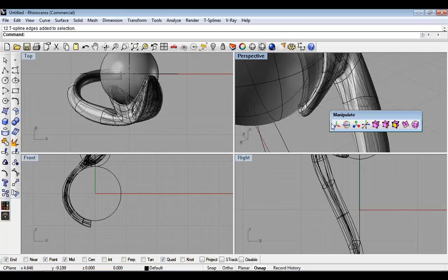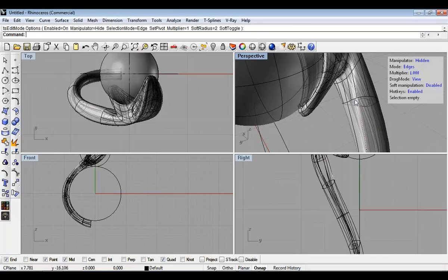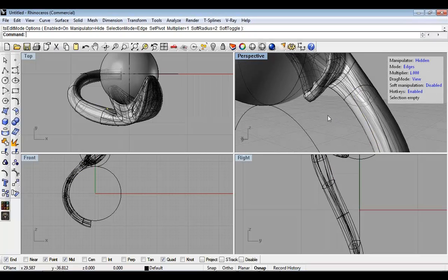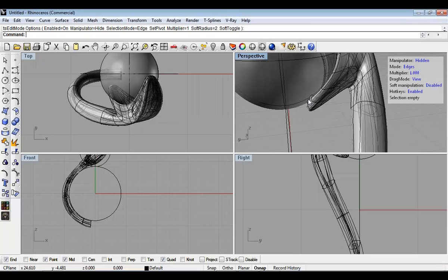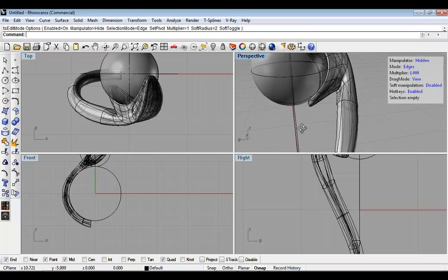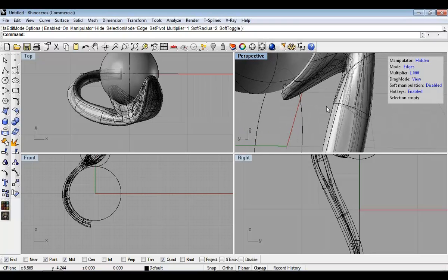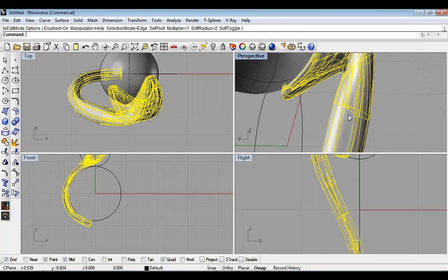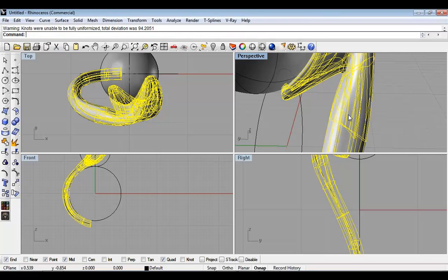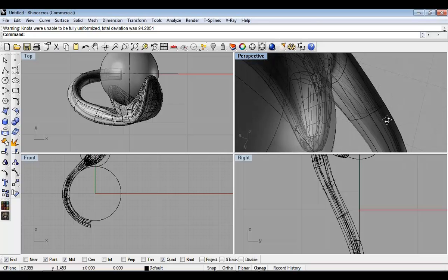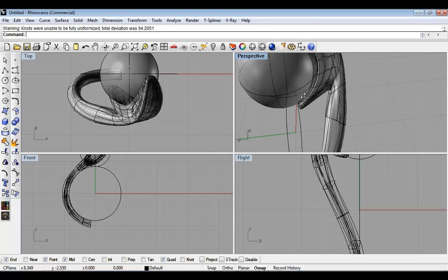Sorry guys, one trick, Chris, are you familiar with the make uniform command? I am familiar with it, and I find that sometimes with tiny small things like this, it can change my geometry in ways that I'm not anticipating. You know what? Let's give it a go. Let's give it a go, man. TS make uniform. Yeah, it looks like it didn't really affect it much, did it?